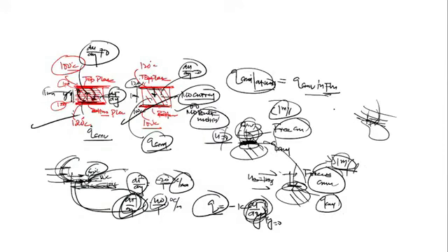That's why I told you, listen, how much importance fluid motion has in the study of heat transfer. Yes or no? Whenever I'm talking about convective heat transfer, the fluid motion will always play a very important role. Because that velocity gradient increases the temperature gradient.